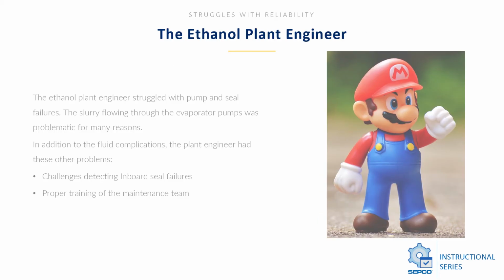At this one particular plant, we were dealing directly with a plant engineer who was struggling with seal failures, specifically in this evaporation process, the evaporator pumps, where they were trying to remove those solids. In addition to those problems, the engineer had other problems, which were detecting inboard seal failures and proper training of his maintenance team.